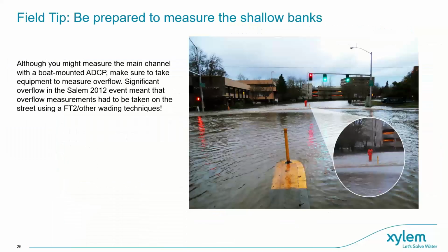All right, and a final field tip for this case study: be prepared to measure your shallow banks as well as your deep flows in a flood event. So in most cases, when you think flood, you think, okay, you'll probably take your ADCP out on a boat-mounted system or on a float tethered to a bridge, that sort of thing.